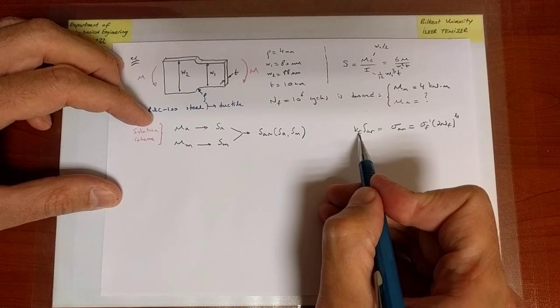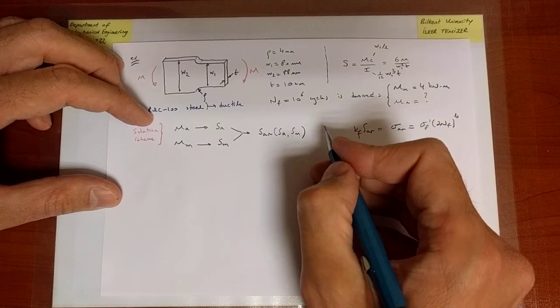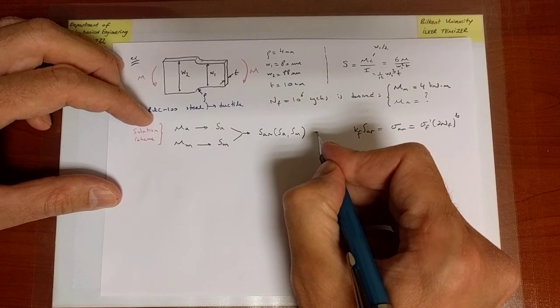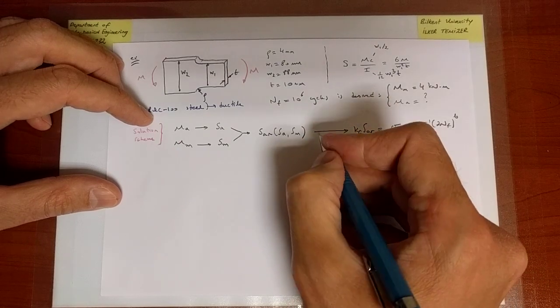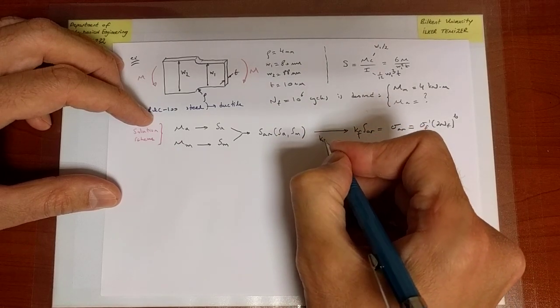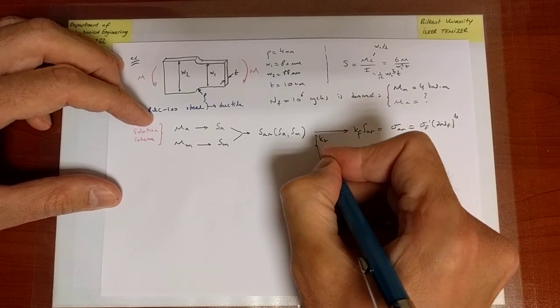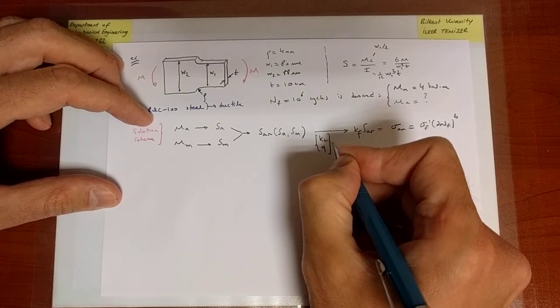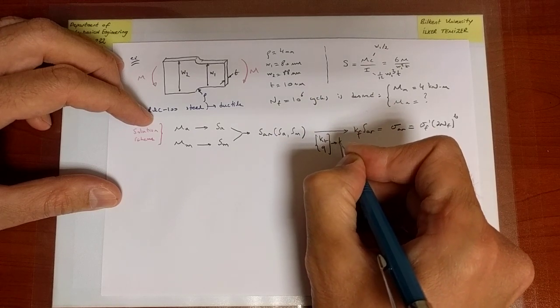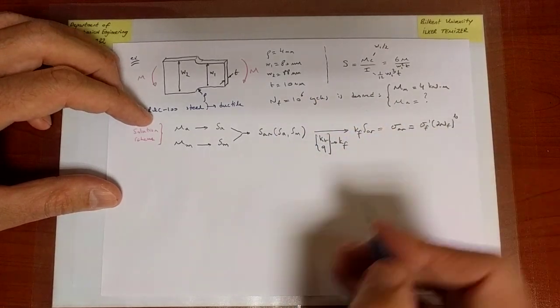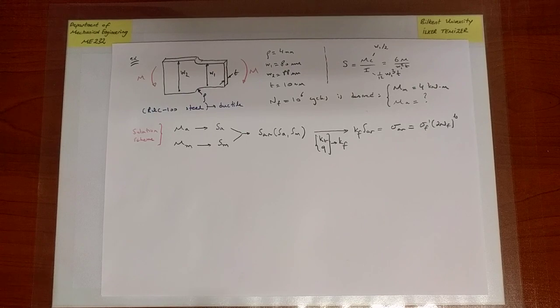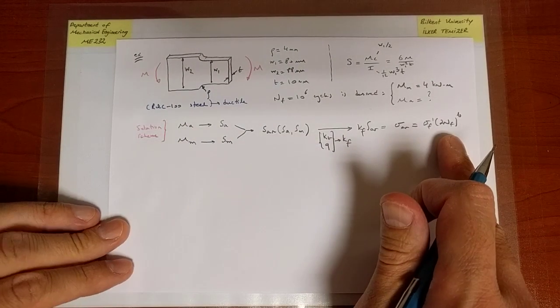But that factor is not the elastic stress concentration factor, but it's actually the fatigue notch factor. So we need an additional map here where we take the actual elastic stress concentration factor, additionally calculate a notch sensitivity Q, and then using these I need to calculate KF and then proceed with the rest of the map. Okay, so starting here I end up there.